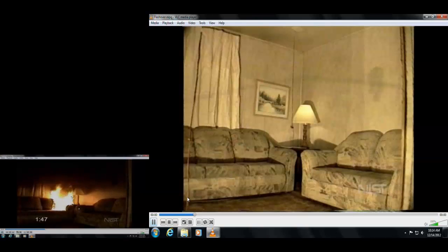Now, you're going to see the layering here. So by 2 minutes or so, you see a distinctive layer between the relatively cool lower layer and the hot upper layer. This is, again, from a modeling perspective in fire, we oftentimes use a two-zone model where we model the cool lower layer as one zone and the smoke-filled upper layer as a different zone.